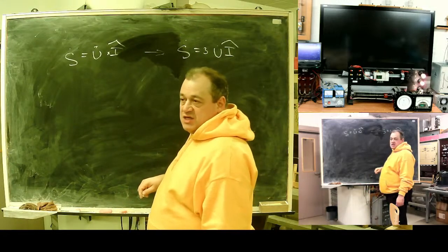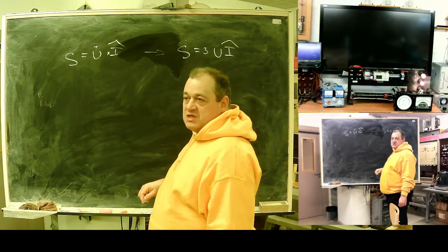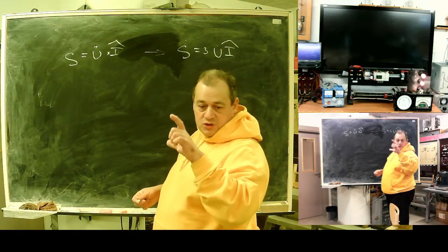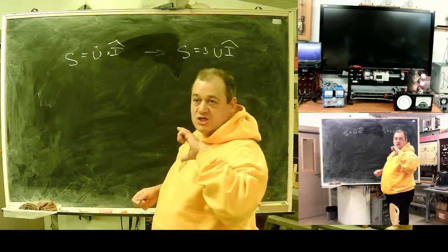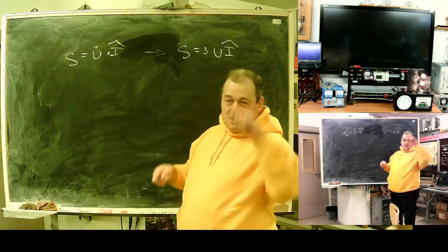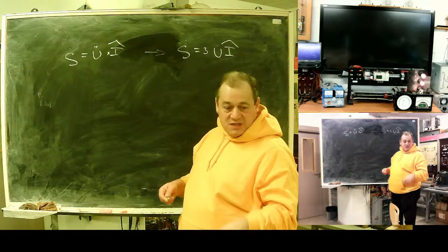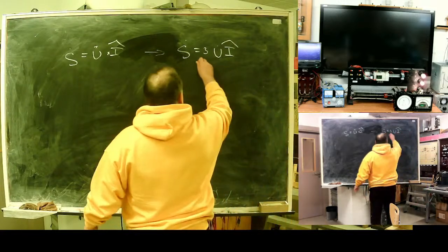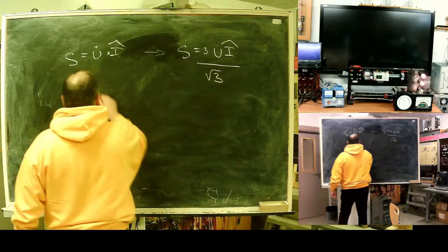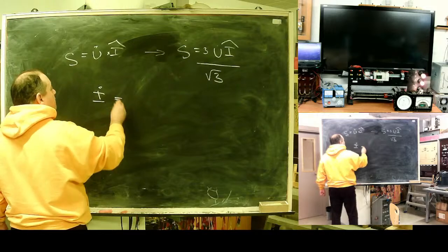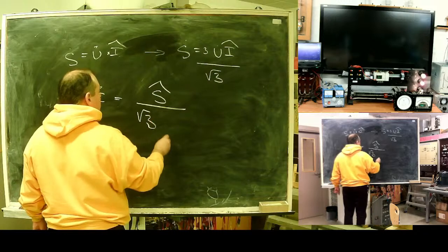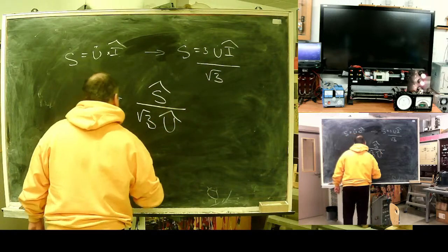And here tradition hits. In such kind of calculus, because of tradition, we can use line-to-line voltage or phase voltage. Tradition asks to use line-to-line. 110 is line-to-line. 10 kilowatt network is line-to-line. To be line voltage, I need a square root of 3 here. So current will be power with conjugation divided by square root of 3 and by voltage.